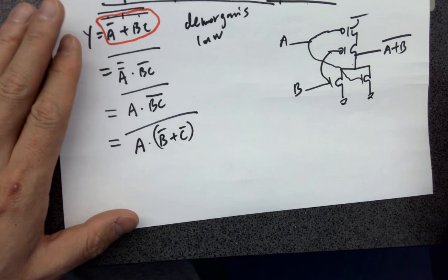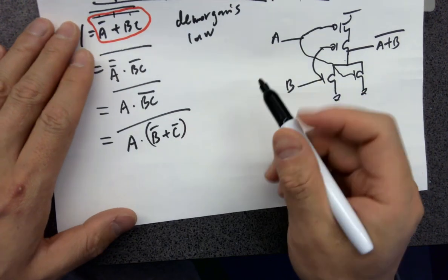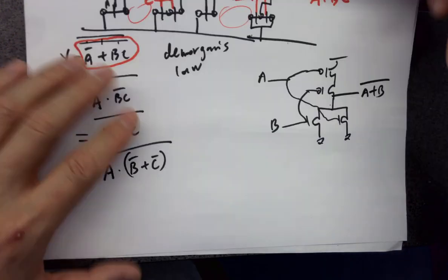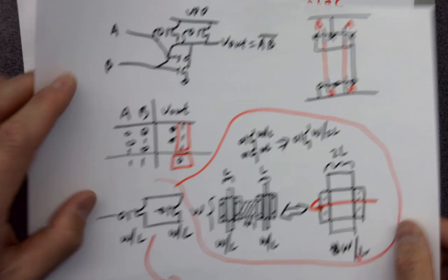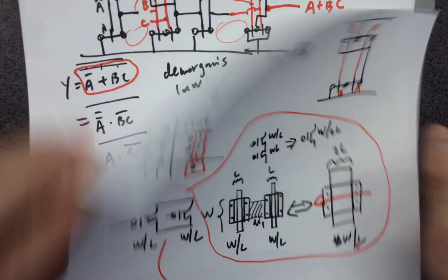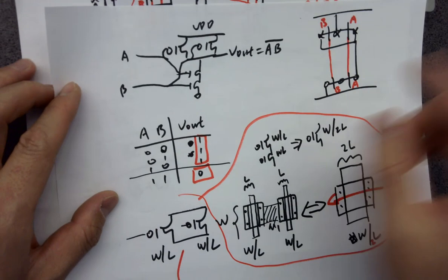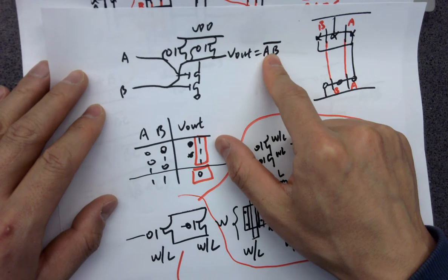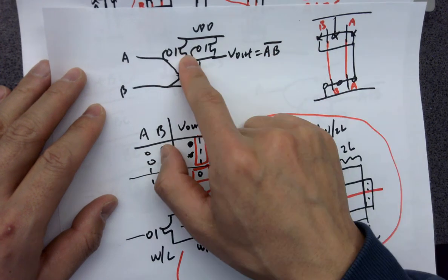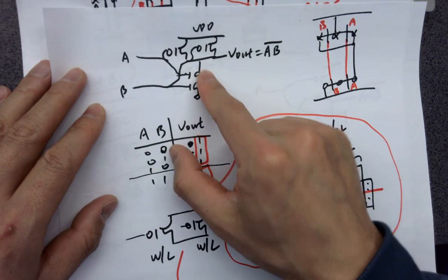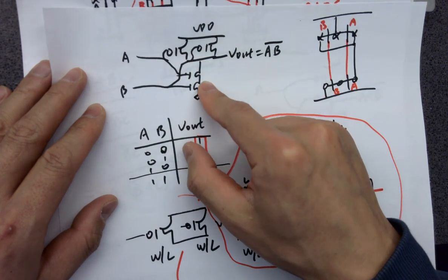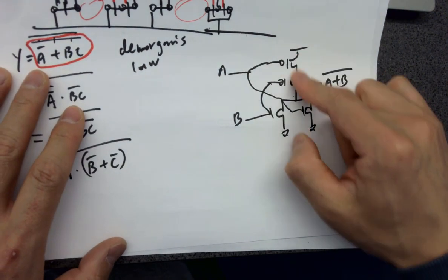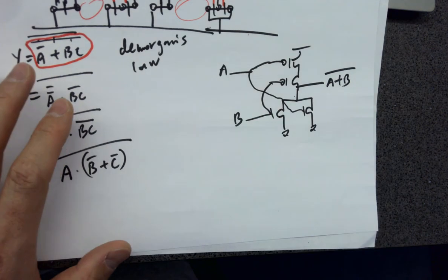Okay? So now we are ready to draw the AOI schematic, because according to the experience we have, or the conclusion we have, we know that, think about the NAND gate and NOR gates, right? For the NAND gate, if you have AND logic under the bar, you are having a parallel PMOS and NMOS in series. If you have an OR logic under the bar, you need the PMOS in series and NMOS in parallel. So that's a conclusion, okay?